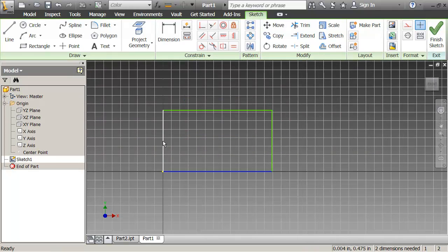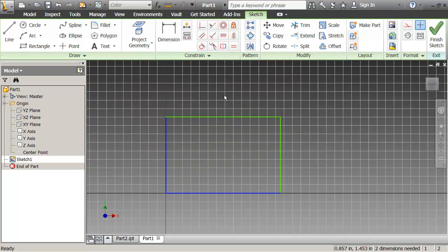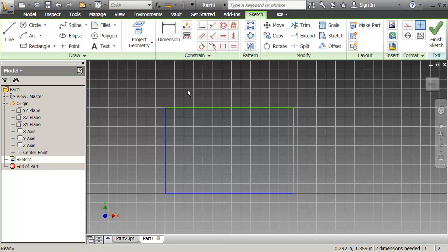So just let me point out that the color blue means that constraints were applied when the rectangle was drawn. Because I drew this approximately horizontal and approximately vertical, it's got these constraints already on the model. You can pick a constraint and apply it. And I think what I want to show is that if I make a change in this, let me put dimensions in to show how I can put additional dimensional constraints on it. So there are geometric constraints there.